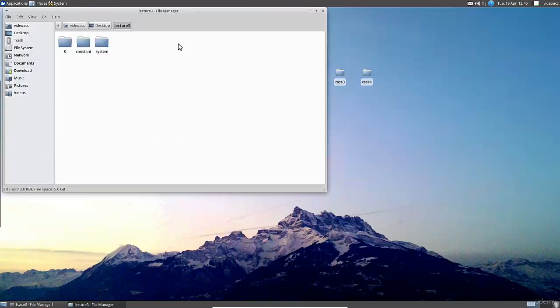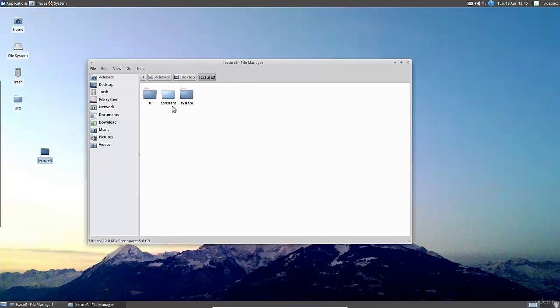Okay, let's have a look at the files. First of all, the 0 folder. It will be a laminar simulation, so delete the epsilon file, the k file, and nut, it's not needed. This is the turbulent viscosity. Delete the R file too, it's not needed.